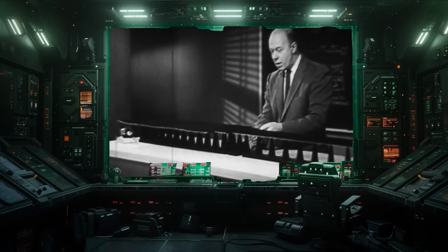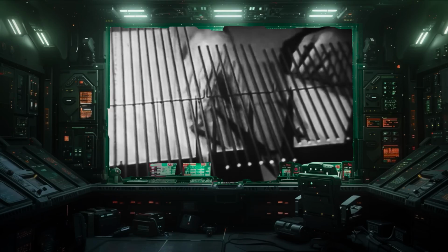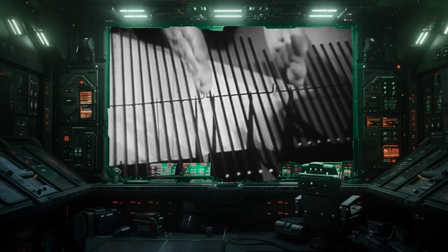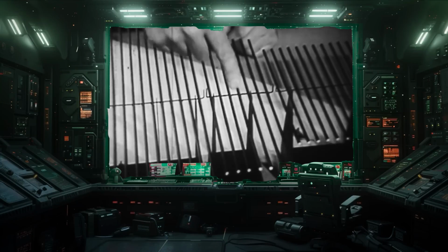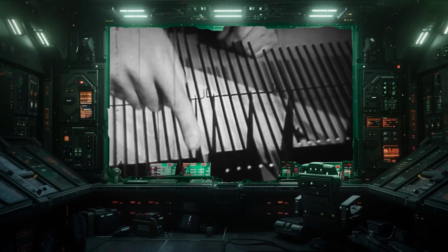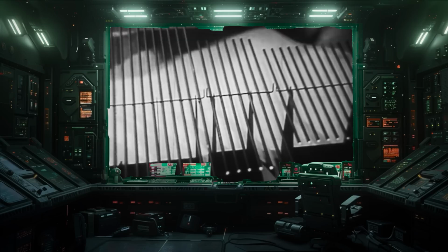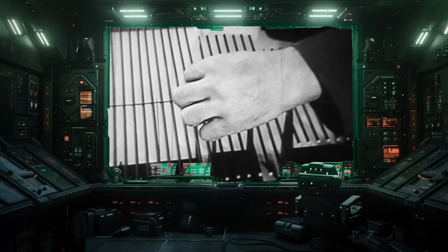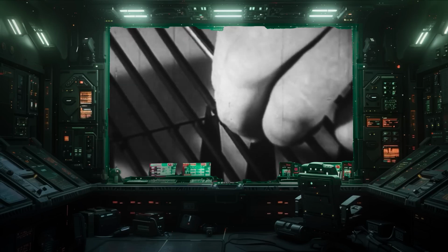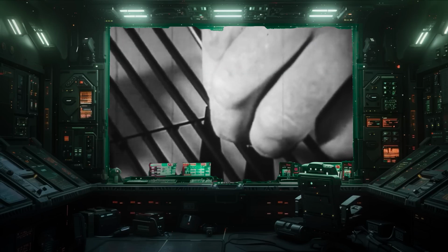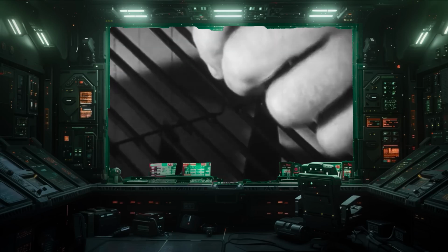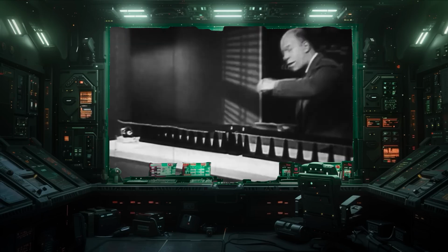It is simply a short section of the wave medium, exactly a quarter of a wavelength long, and having a cross-arm length intermediate between the cross-arm lengths of the two machines. It is called a quarter wave matching transformer. I'll sandwich it in here and then show you how it operates to promote the transmission of wave energy across this discontinuity without reflection loss.